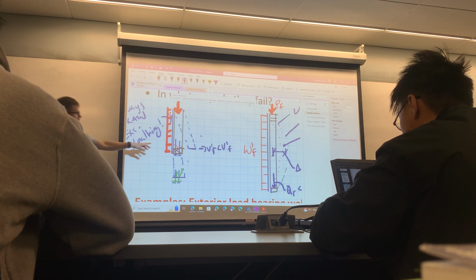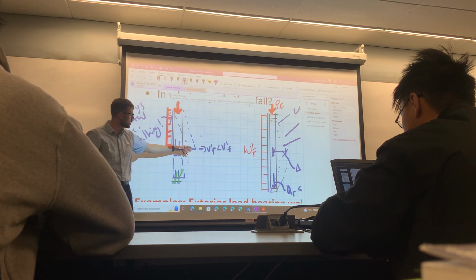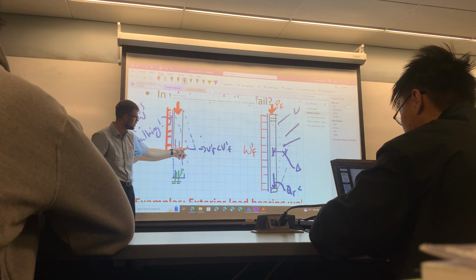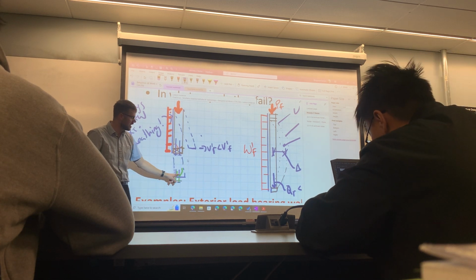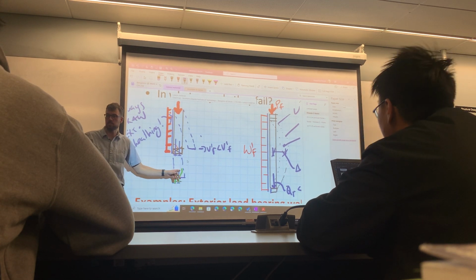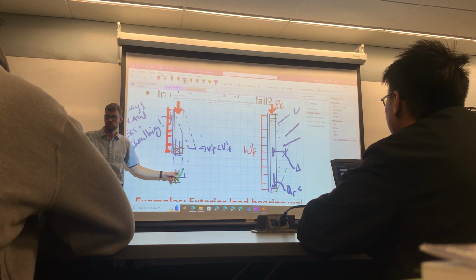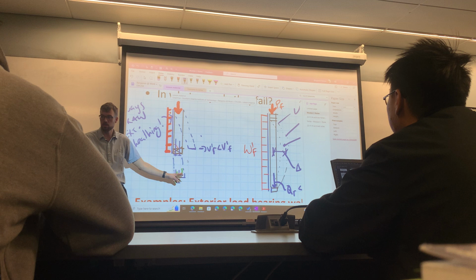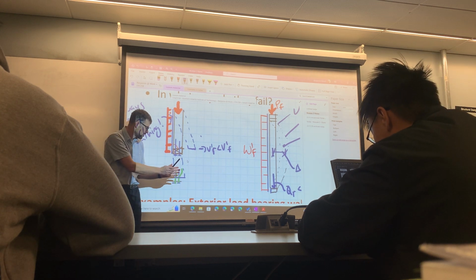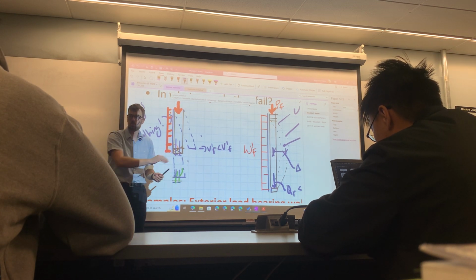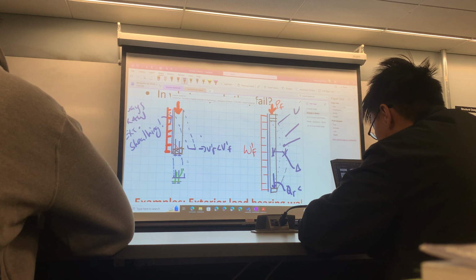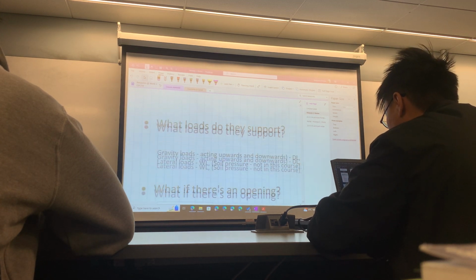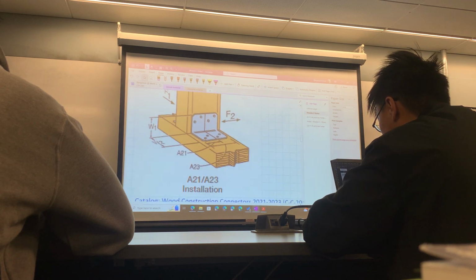So you either have this shear failure where it comes off and it breaks the wood, or you've got bending of the nails. Has everybody kind of experienced bending of nails before? Right, eventually you push on these basically really slender columns, you'll push on those, and eventually they'll bend over. Like if you take a paper clip, push on the paper clip, that's gonna bend over. So then what we do is we start adding reinforcement.